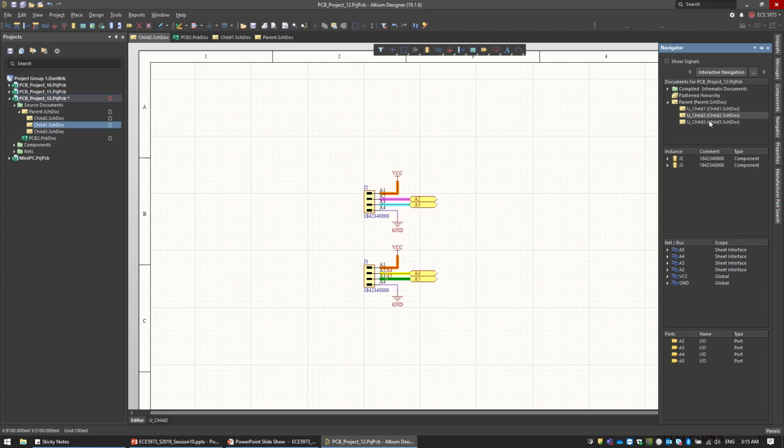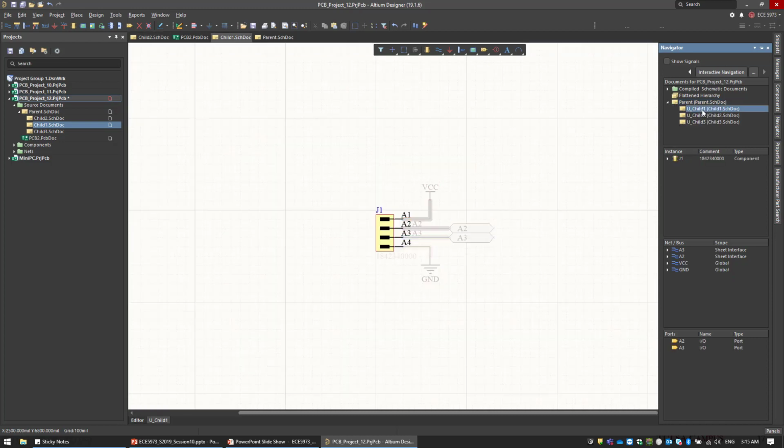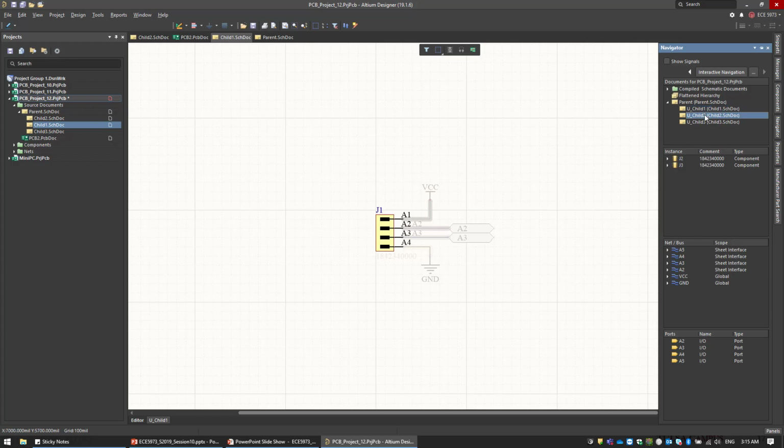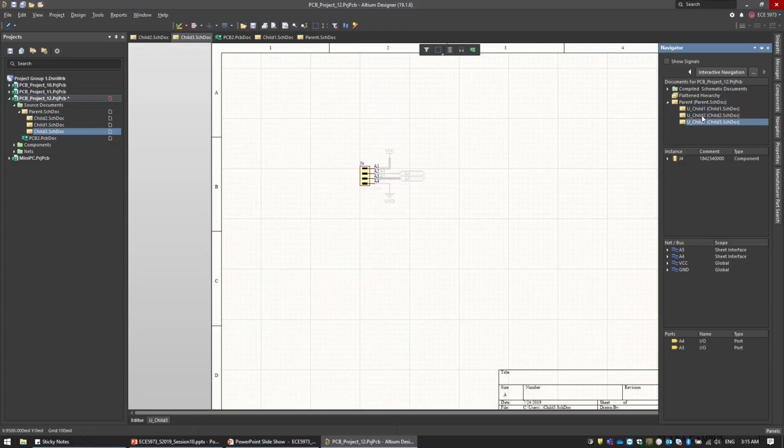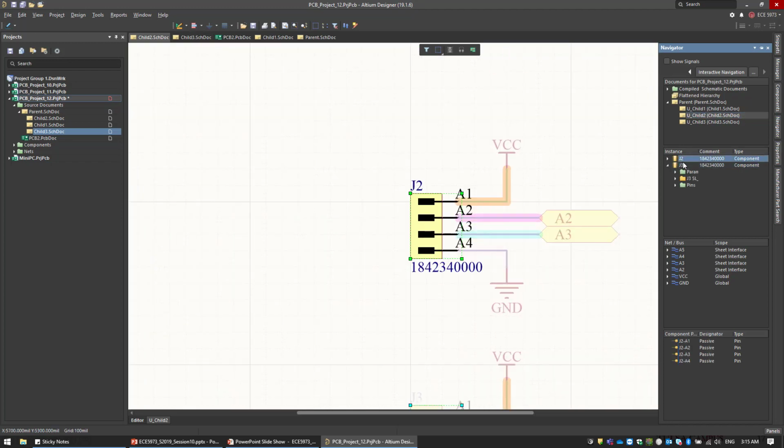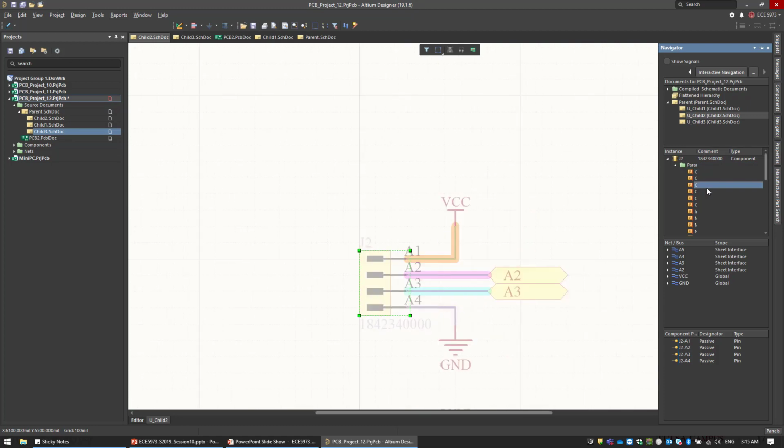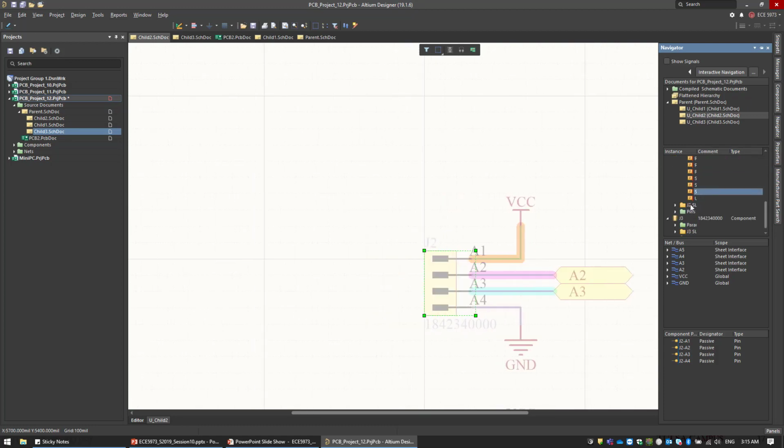We should open a much more complex design, but you can see that you have a parent sheet, and you have child 1. You double click on it, it will take you to child, then child 2 and child 3. And on child 2 you have 2 connectors, and on the first connector, these are the parameters for the connectors, as you can see.